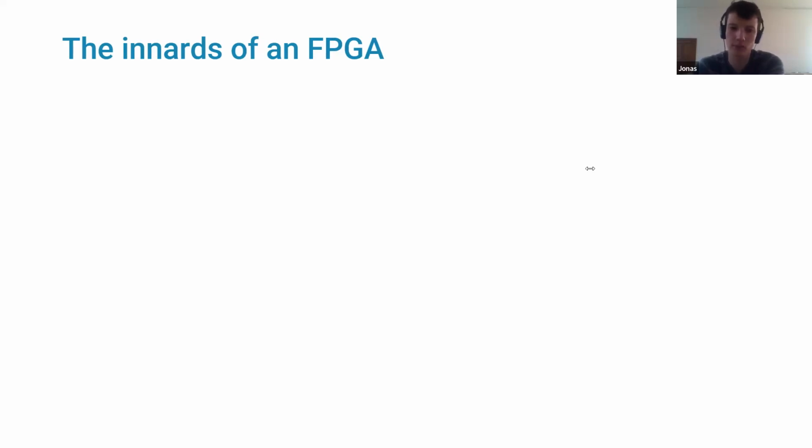It's also going to be a bit more of a struggle, specifically because, for people who don't know what SLRs are, Xilinx creates its bigger FPGAs by stacking multiple smaller FPGAs together, and then having these things called SLR crossings between them. So they turn a whole bunch of FPGAs into one glued together FPGA. But then the problem is, how do you communicate between those smaller, quote unquote, smaller FPGAs, because these are still very big FPGAs.